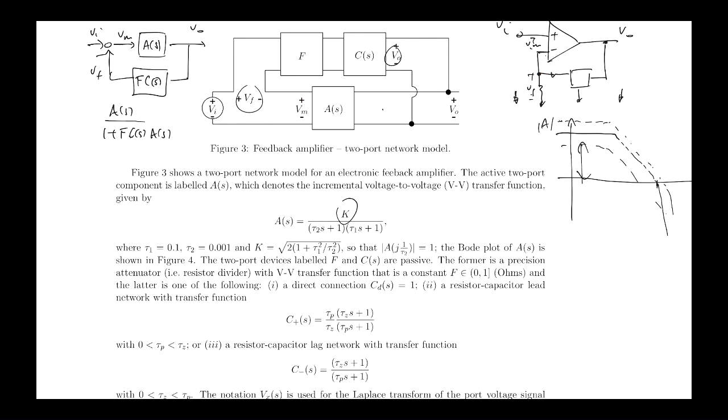So it's just Kirchhoff's voltage law around there gives us this element of our block diagram, okay? The transfer function of the op-amp relates VM and Vout, right? And then VF is related to Vout by the characteristics of the feedback network, right? So that's F, the resistor divider, plus whatever compensator we put in there, right? So it's a standard closed loop system, all right?